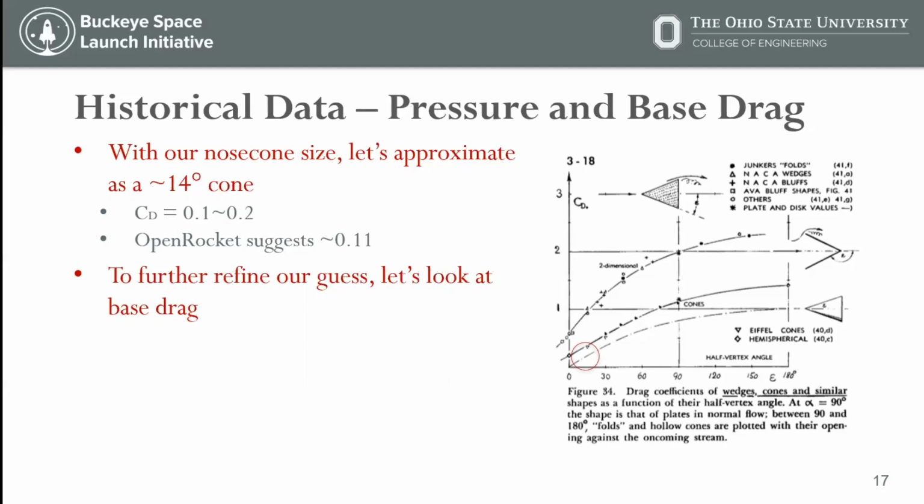So Nate says, why do we use a von Karman nose cone? Correct me if I'm wrong, Nate. There's a couple of reasons why you might want to use it. The reason why we used it was convenience, because we had a mold for a von Karman nose cone. Okay, that makes sense. Going off of just memory, I don't think von Karman actually offers too many benefits in the subsonic regime. Supersonic is by far the most efficient. Right, that's why we use it on the Spaceport America rocket. But I think this year it was out of convenience, because we could save a little money on materials and making a mold. So we did use a von Karman nose cone this year.